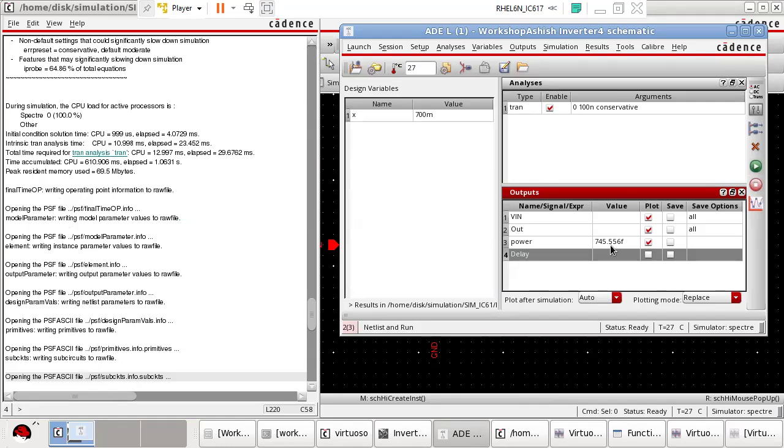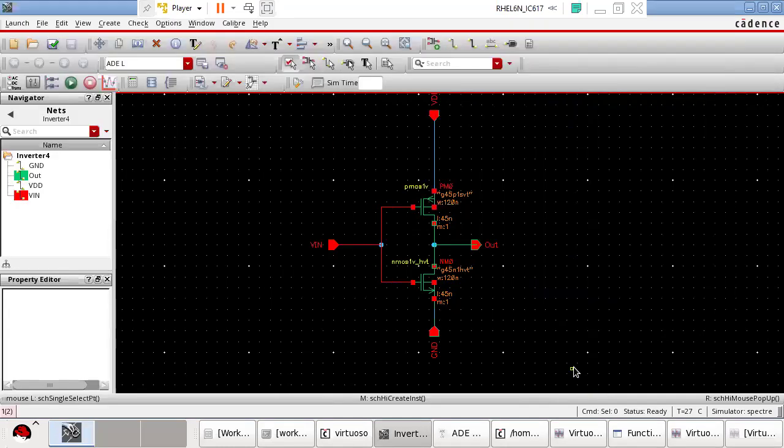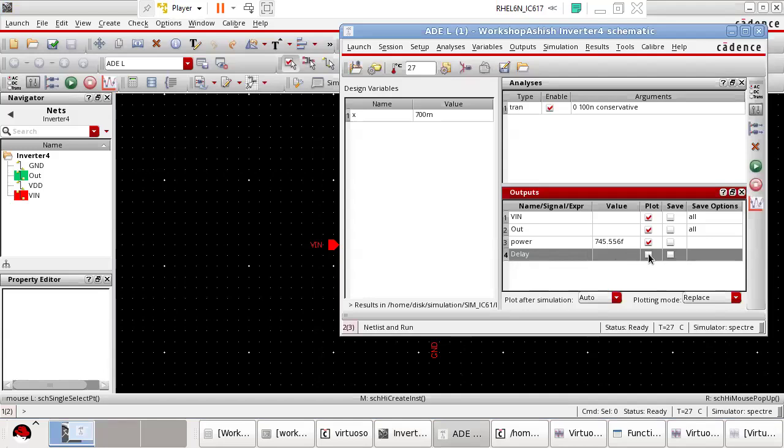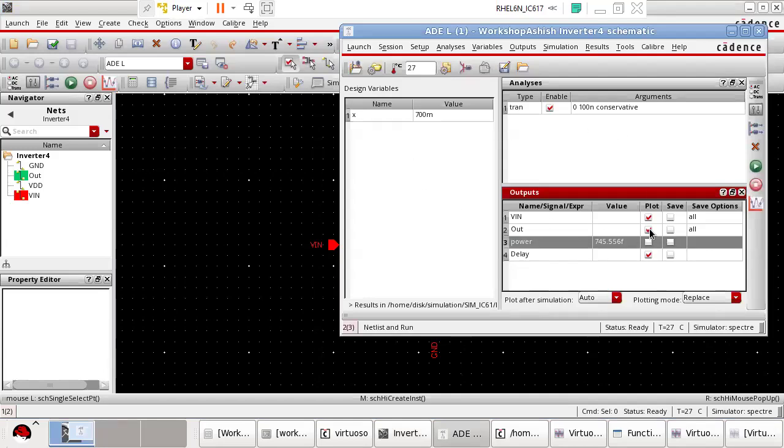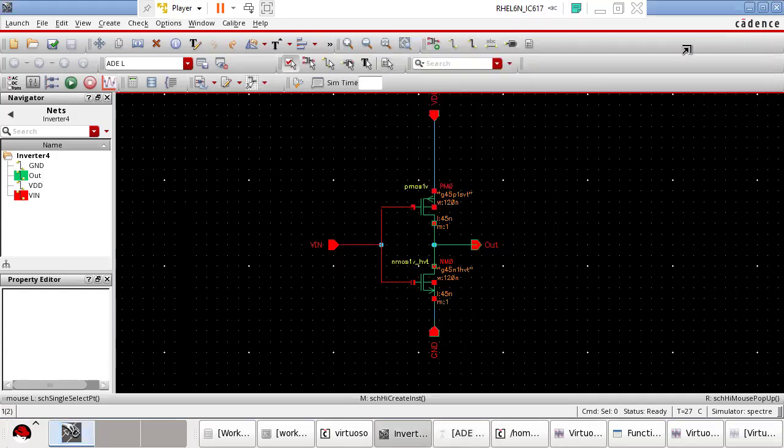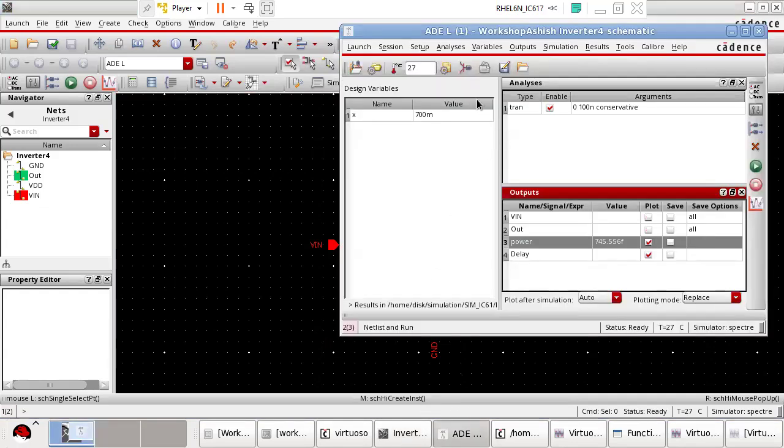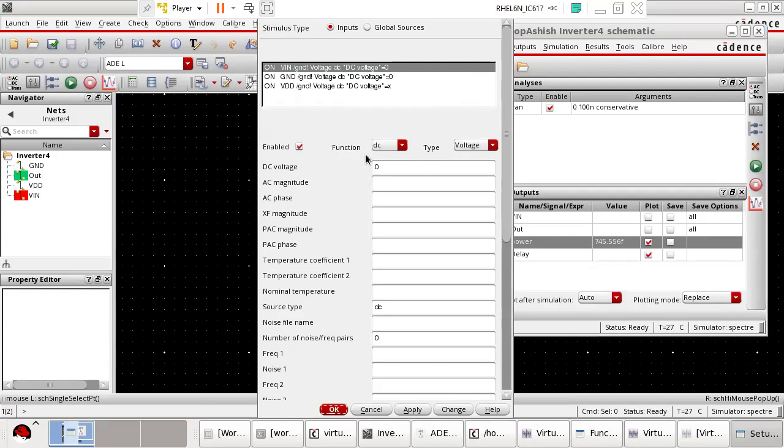But the question is, if it is that simple, that you need not increase the size of the device, you need not do anything, and your leakage is reducing, why don't we use it? Remember, without using this device, the delay of my circuit was 47.048. And now what is the delay in this circuit? For delay, I need to give the switching voltage.